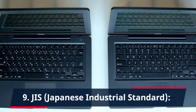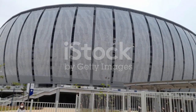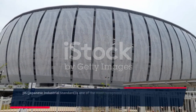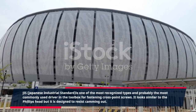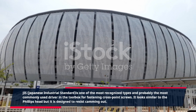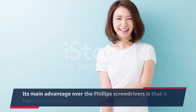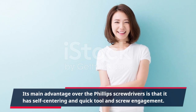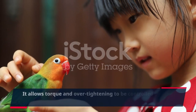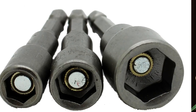9. JIS, Japanese Industrial Standard. JIS is one of the most recognized types and probably the most commonly used driver in the toolbox for fastening cross-point screws. It looks similar to the Phillips head, but it is designed to resist camming out. Its main advantage over the Phillips screwdriver is that it has self-centering and quick tool and screw engagement. It allows torque and over-tightening to be controlled by the operator and not by the head of the screw.